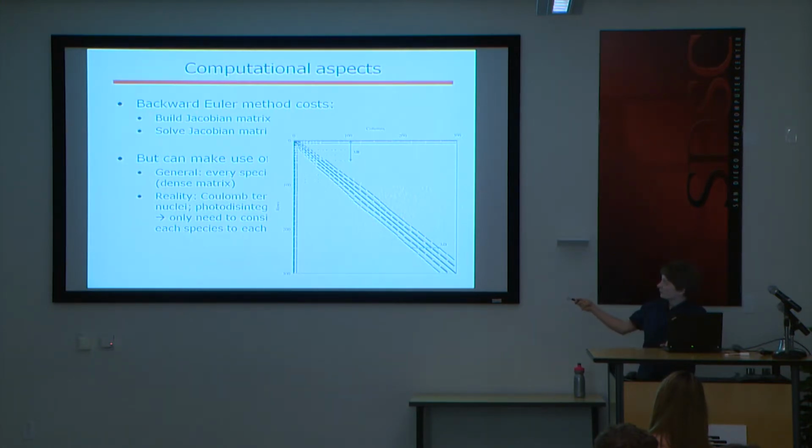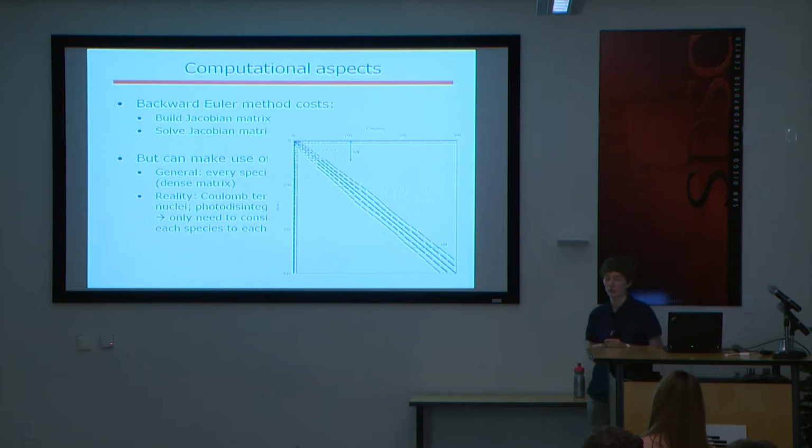All right, so by what we know about the system, we have to go to an implicit method, but we can use sparse matrix solvers. And computationally, it makes a difference using a sparse matrix solver. The other thing that cuts down on your computational costs is, instead of storing every element of this matrix, because it's sparse, there are specific formats to store sparse matrices where you only store the location and the value of the non-zero elements. So you can also cut down on memory use if you know that you have a sparse matrix and you use these specific formats for sparse matrices.